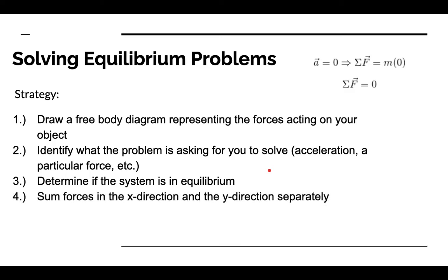You're going to sum the forces in the x and y direction separately. Again, remember, I can't emphasize this enough, that the forces must be summed separately. They're independent. And then you solve for your unknown quantity.